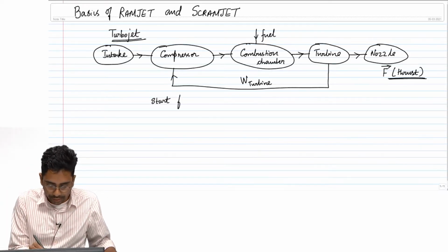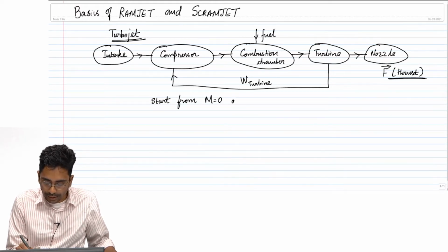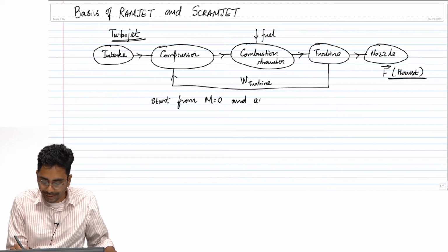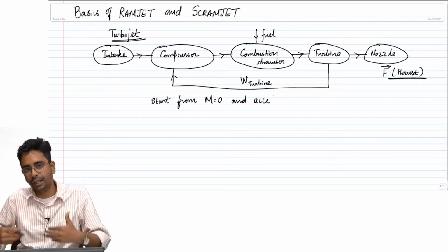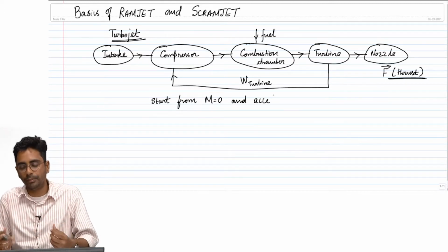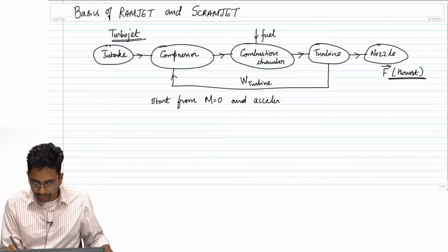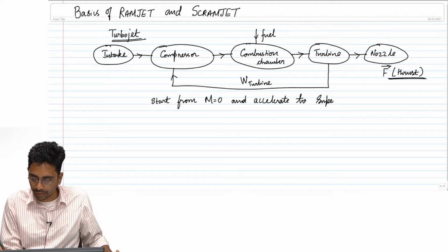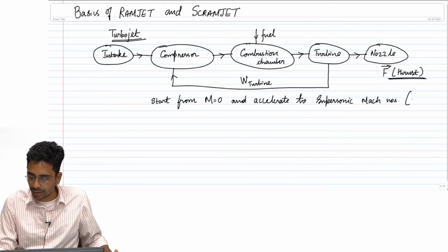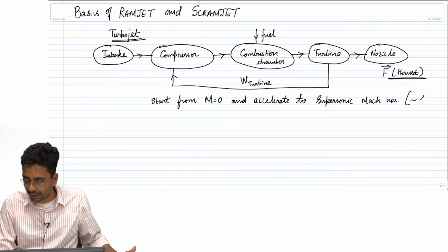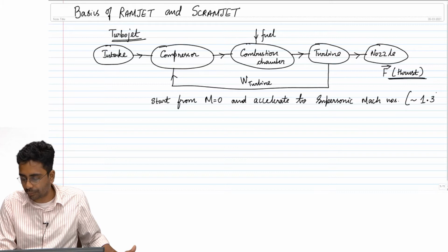This is a key point. To accelerate, you need force, and therefore, at Mach 0 itself, the engine should be able to produce a positive thrust, and accelerate to supersonic Mach numbers. Please go and look it up. I think it's about 1.3, 1.4 and not more than that.